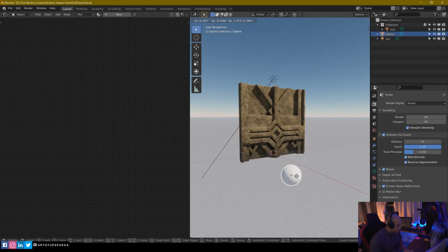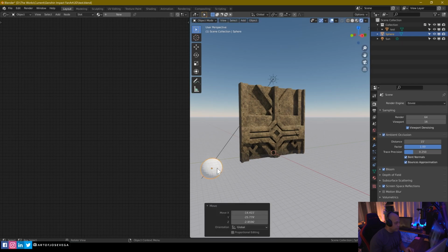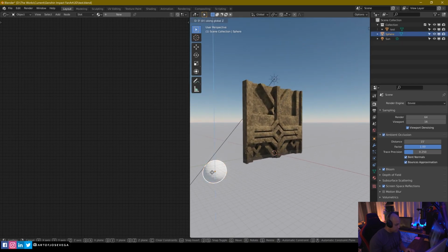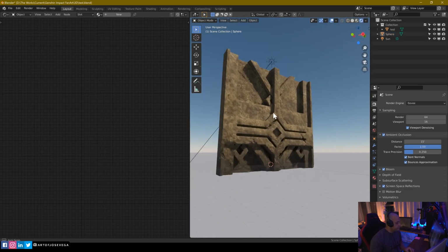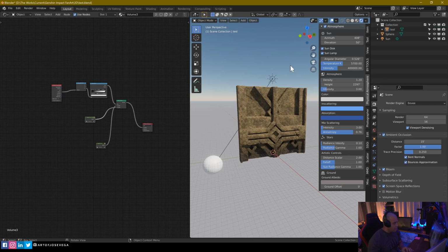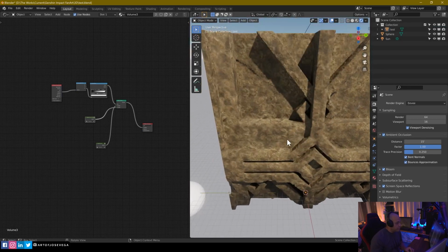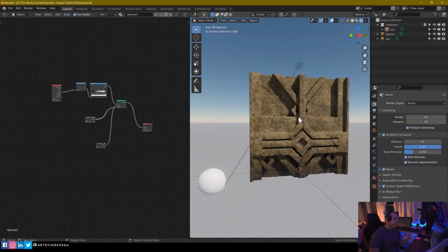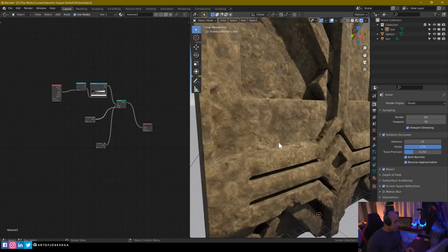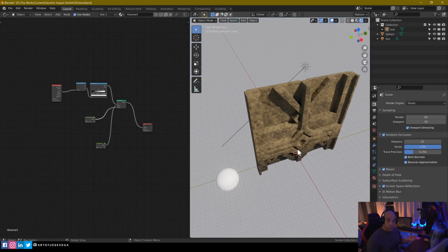And now I can place this sphere wherever I want in terms of the Z-axis to control how much of that darker. And I don't want too much, I just want a little bit here like that. That way there's a little bit of difference as it goes up. Now you can tweak depending on how specific you want to get, but this will give you an idea of the whole process of creating an asset. From using stencils to taking it into Blender, decimate it, bring it into Mixer, texture it, and then bring it back into Blender to finish it up and then create your own kit.